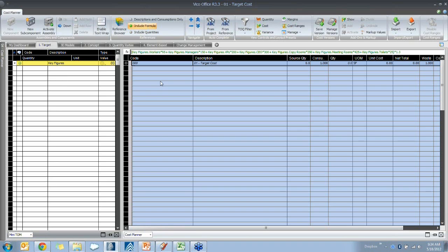And on the right-hand side, we have what we call the cost plan, which is much like an Excel table, but plus the power of a database, being able to reference information from other projects and reference information from this consolidated list of quantities. And really worthwhile to note as well, this list of quantities consolidates quantities from manual inputs that we'll show in this target phase. It can have Excel imported quantities and consolidate also many different BIM applications, the models, quantities in the same list.